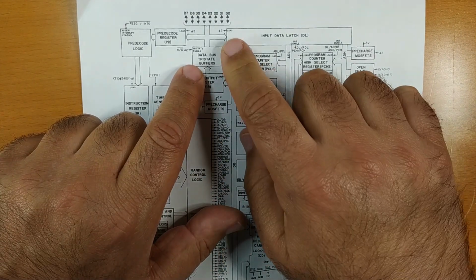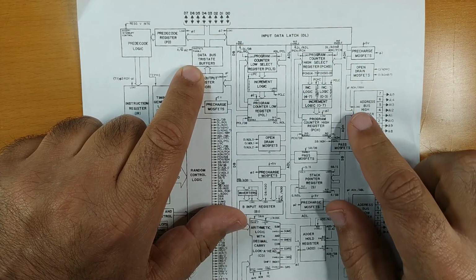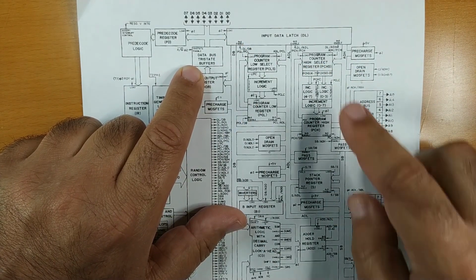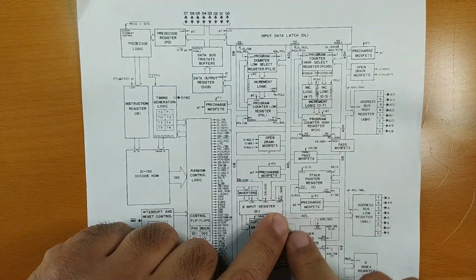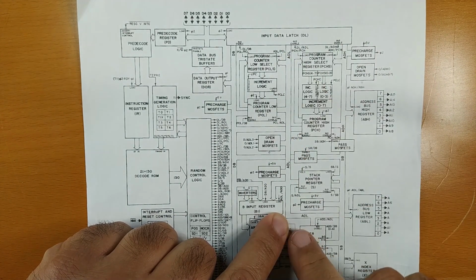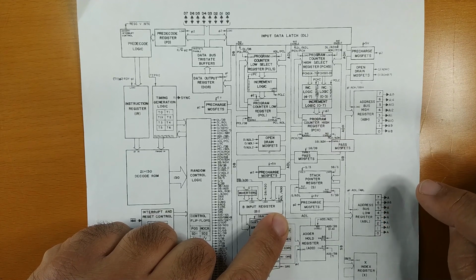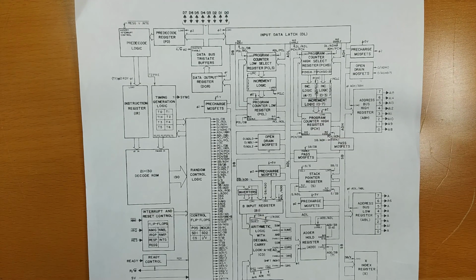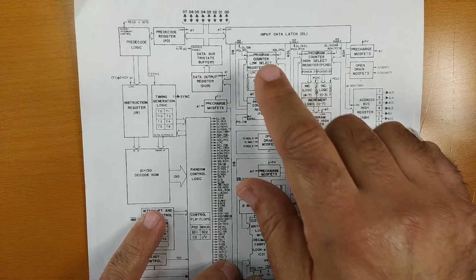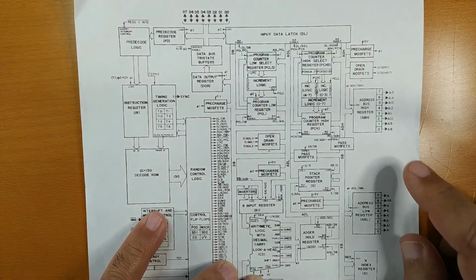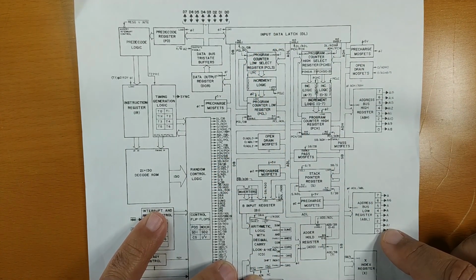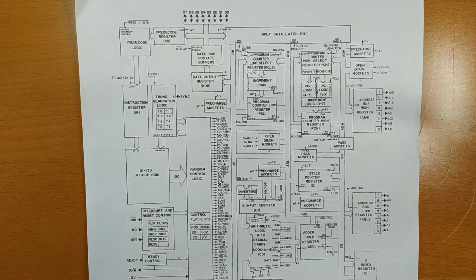And we see that both the data latch and the registers, this is the address bus low, which is the least significant byte, both have a load control, which means exactly what we just said. We have a latch on the input and we have latches on the outputs. So great, we have the right idea.